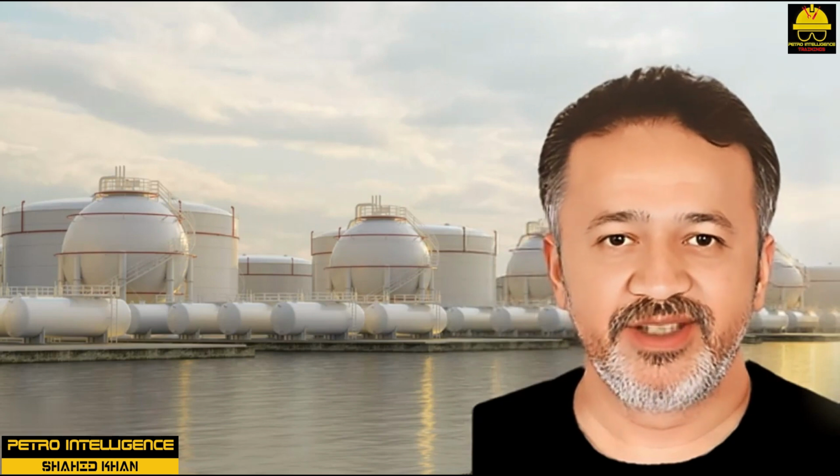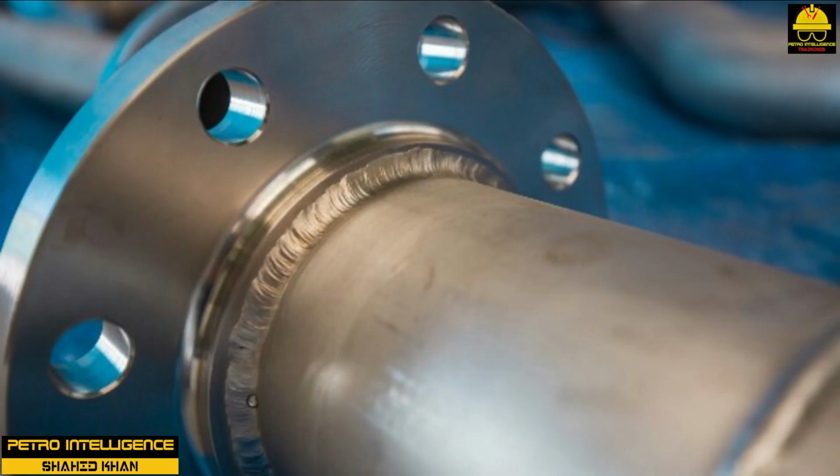Austenitic or stainless steels. When both nickel and chromium are added to steel in amounts totaling somewhat over 20%, the microscopic structure undergoes a pronounced change. The small grains of which steel is composed solidify in a form known as austenite, which behaves in many respects quite differently from the steels previously described. The most common composition of stainless steel is commonly referred to as 18-8. This name comes from the fact that this stainless steel contains about 18% chromium and 8% nickel.